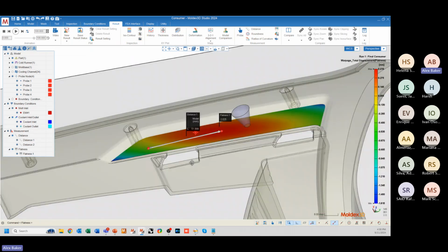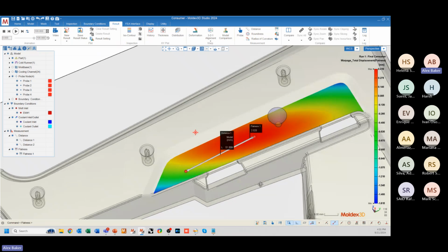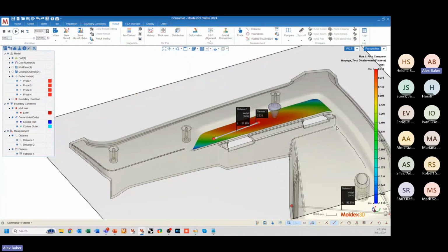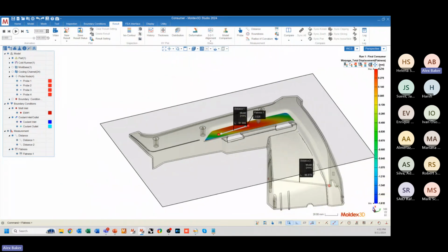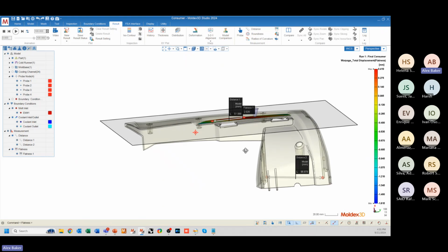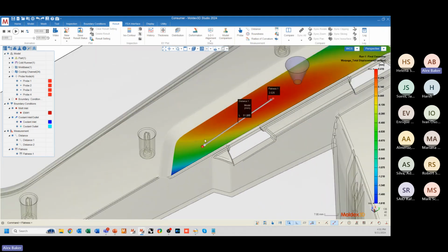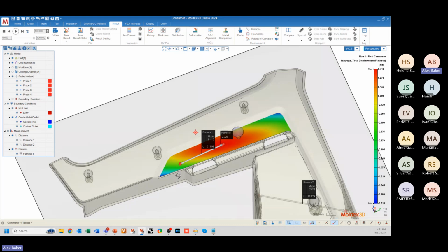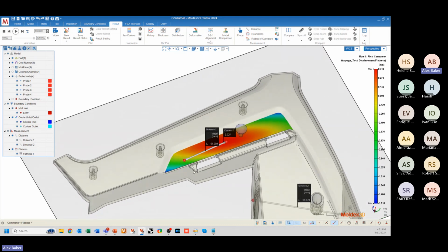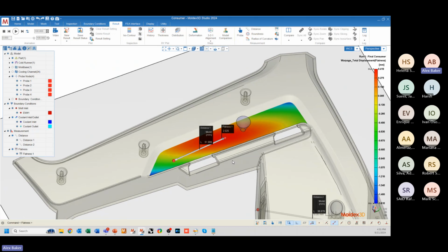Save and close. You can see a pretty similar color distribution. It's inversed because it's more of a deviation from the flatness plane. So the colors themselves look pretty different, but the actual contour, or the actual information you're getting from these two tools, is very similar.